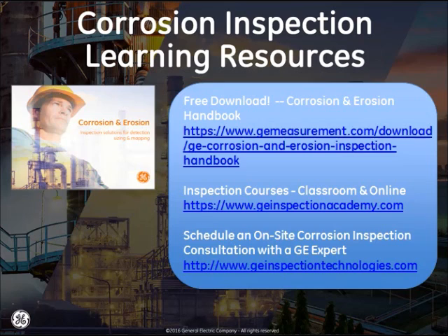Typically, when a facility is designed, the design engineers specify critical areas for corrosion mapping to be performed. So they specify where the suspect or critical areas are. So that's typically where the inspections are initially done.